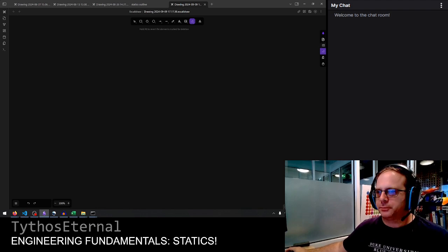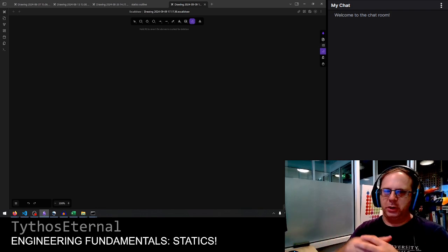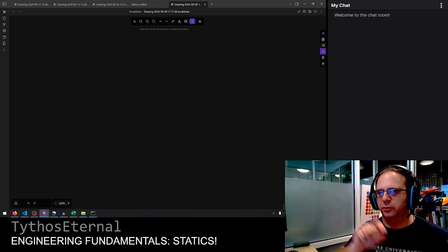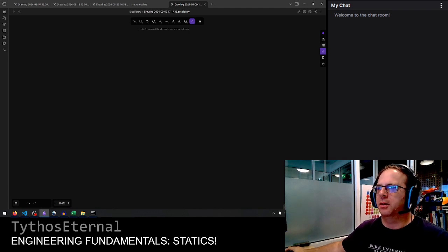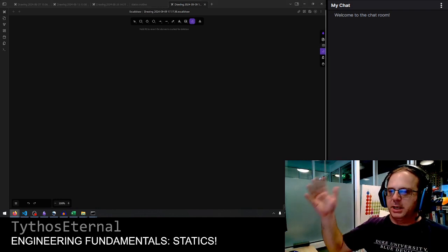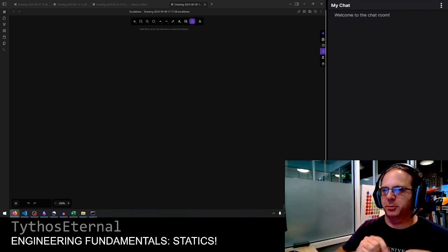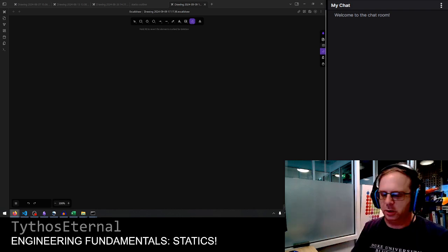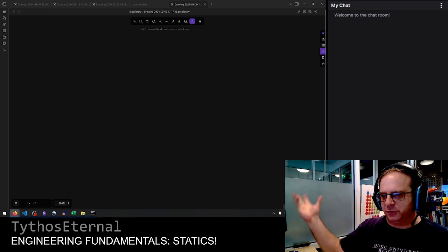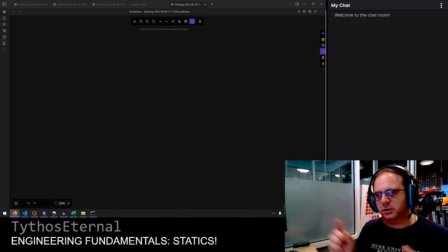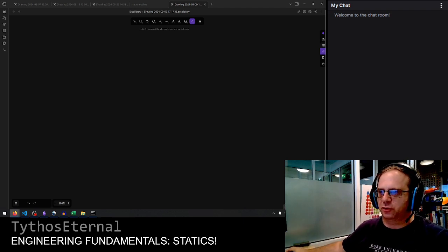Etc. If you recall, when we're talking about systems of knowledge, the number of constraints you have in a system has to equal the number of degrees of freedom if you want to solve for specific values in a system of equations. That's very much applicable here. We have, say, a bridge or a building with a wide variety of degrees of freedom. There may be a joint here, a beam there, a pulley there. But we need to place constraints on that in order to solve for what the state of the system is. So given some static load, we may be able to come up with restoring forces here, and that means this force here, and that means this moment here, because we're able to place static constraints on the system.